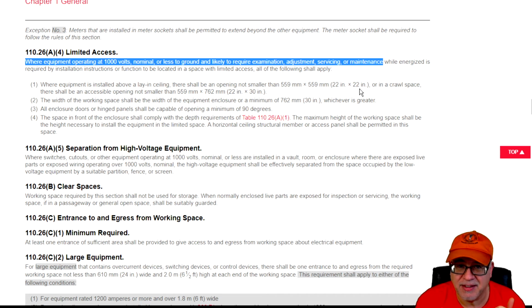Okay? Well, when it goes bad, it's just replacement. And that's a requirement to have disconnects, and that's in 450, the rules for disconnect to be able to turn it off and lock it and be able to do a replacement. Okay? So, transformers, for example, you got to think sometimes people are requiring a lot of weird things, and you really need to look at the application. So I use this example, even though we're talking about limited access, for the disconnect outside to an air conditioning unit. Does it require examination of the equipment? Yes. I can tell you right now, my air conditioner fails all the time, and it has to come out, and the first thing they're going to check is whether or not it's got voltage there. It's just a basic 101. We're not going to pull apart that unit just to make sure it's got voltage there.